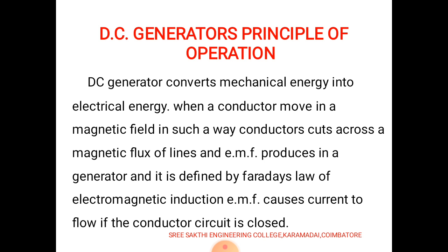Principle of operation. It works on the principle of Faraday's law of electromagnetic induction. According to this law, when the conductor is rotated in the magnetic field to cut the magnetic lines of flux, induced EMF is produced in the conductor. This EMF causes a current to flow if the conductor circuit is closed.